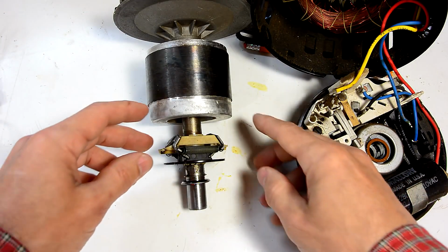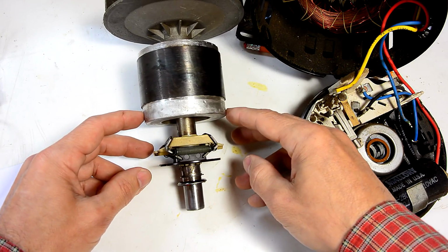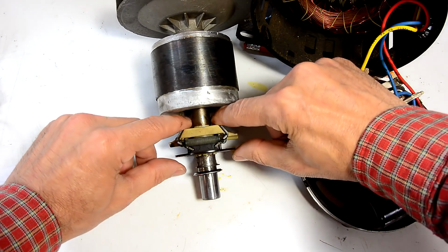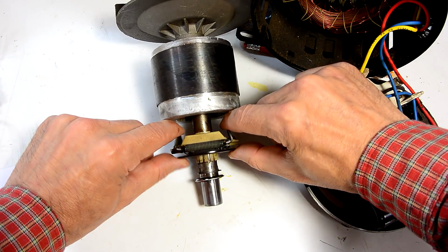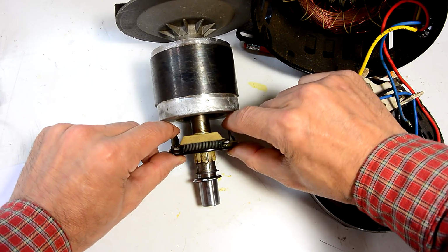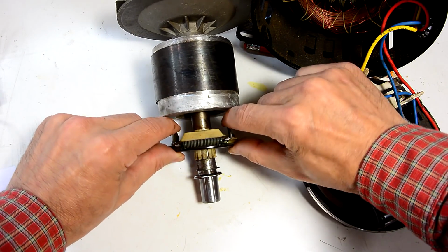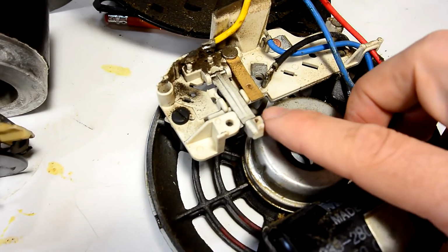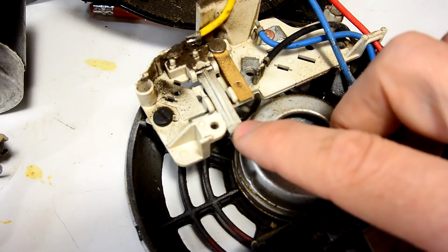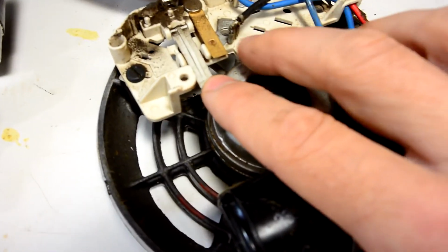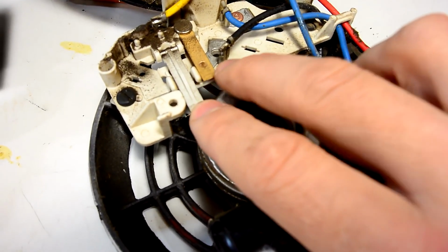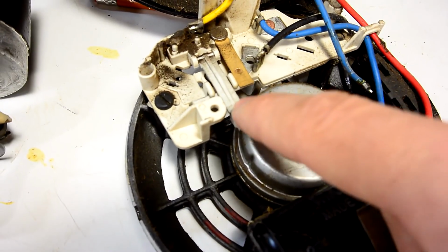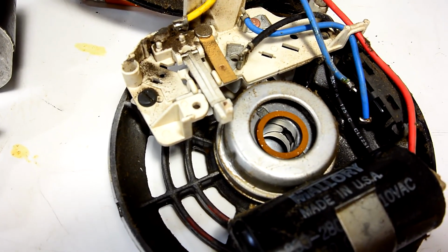The starter winding is automatically turned off with a centrifugal switch, and the way that works is these two metal clips get pulled out by centrifugal force once it spins at full speed, and that pulls back this plate here. When the motor is not at full speed, this plate rubs against this plastic tab here, and as long as that plastic tab is pushed, this starter contact is closed, and then once it's up to speed, the plate pulls away and it no longer rubs against here, so we don't get friction and wear.